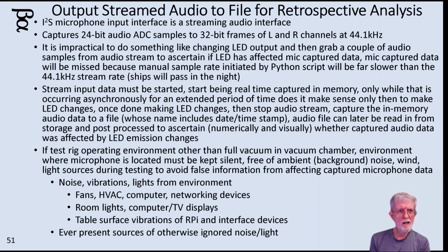If your compressor for your AC unit is a little out of alignment, it can induce vibrations in the foundation of your house that you will likely never perceive. But if you're doing your microphone measurements on a steel table that has direct contact with the floor of your house, let's say in your garage, the microphone's going to pick up those vibrations, even though you can't hear them. All kinds of things you have to say, I need to prove that it wasn't that.